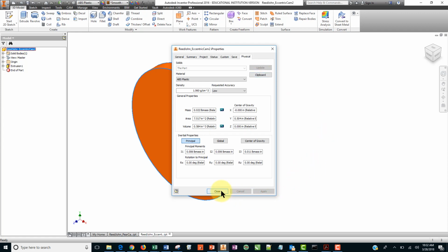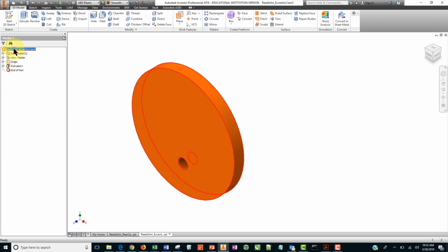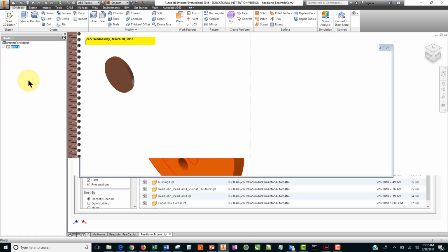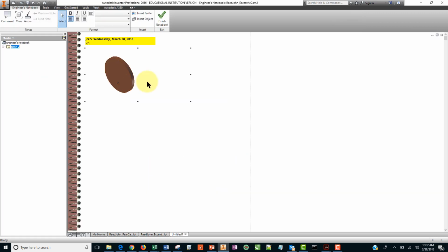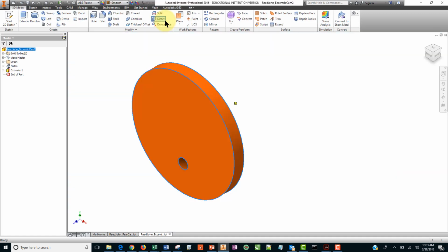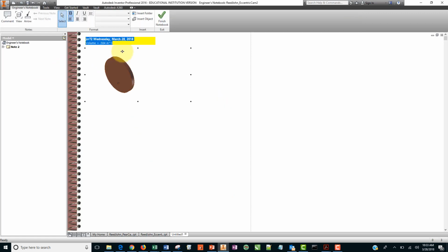Now here's how I want to show you a new trick. So remember that number, 0.584 cubic inches. So if I right click here, create note, volume, I want you to do this, volume equals 0.584 inches, caret is right above the 6, cubed. And can we make that bigger? Not easily. That doesn't matter. We've got a note there. So whenever we want to find out what that volume is, we can double click there, 0.584.